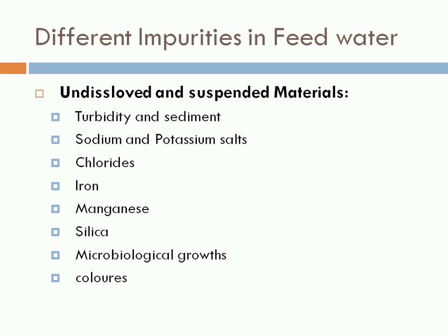So these correct treatments can be controlled by the efficient operator and use of the treatment chemicals, right? The internal treatment is for the boiler feed water, and external treatment is for makeup water. And for the condensate part of the system, internal treatment protects against feed water hardness by preventing the precipitating of scale and different things. And deaeration is also there, then different scale formation, then priming and foaming, then corrosion, etc.